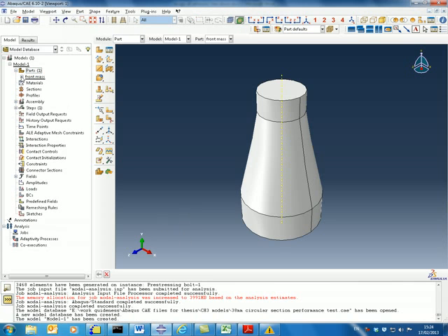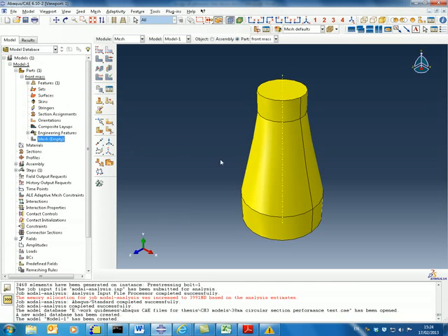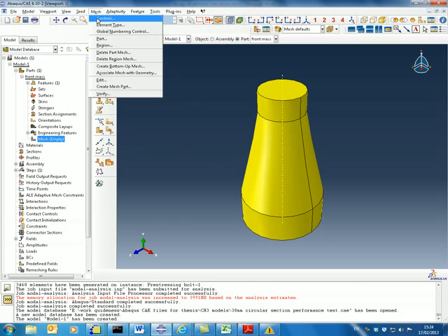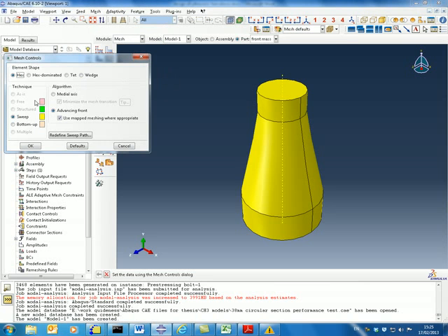Now I've created the first part, and before moving to the next part I need to check the type of construction which can help to mesh the front mass, and you can check which type you have by using the mesh control. So you can see there are different types of technology for meshing.